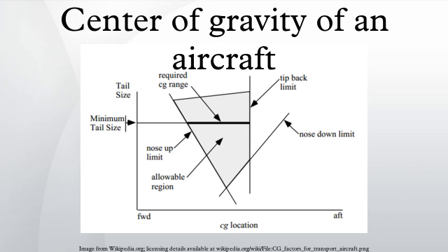Weight and balance. When the weight of the aircraft is at or below the allowable limits for its configuration and its center of gravity is within the allowable range, and both will remain so for the duration of the flight, the aircraft is said to be within weight and balance.